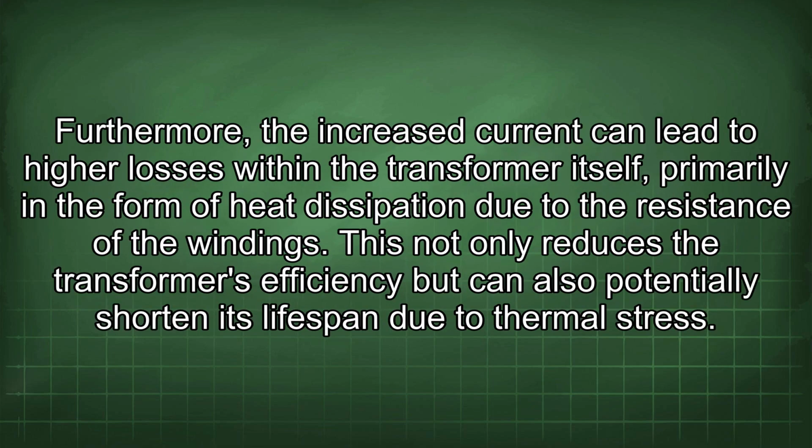Furthermore, the increased current can lead to higher losses within the transformer itself, primarily in the form of heat dissipation due to the resistance of the windings. This not only reduces the transformer's efficiency, but can also potentially shorten its lifespan due to thermal stress.